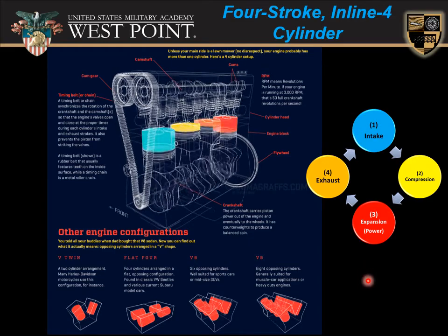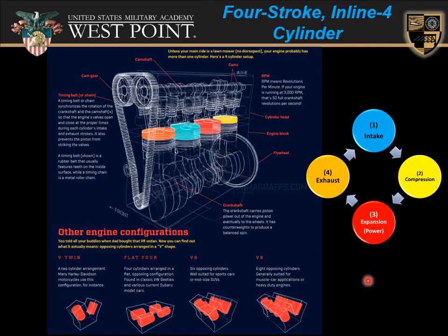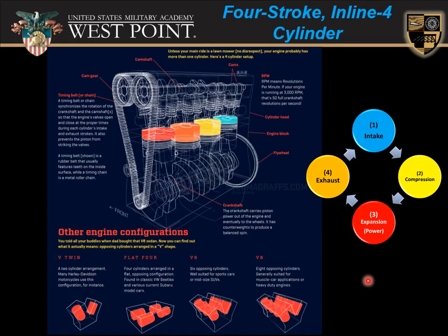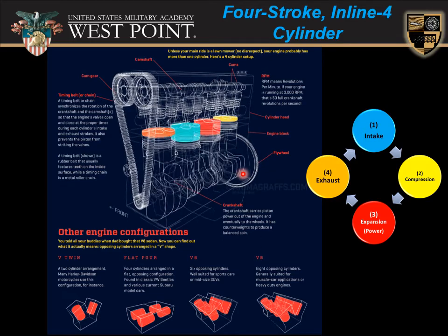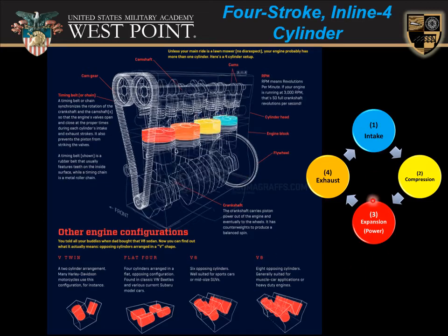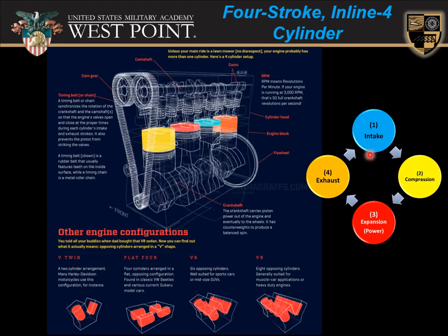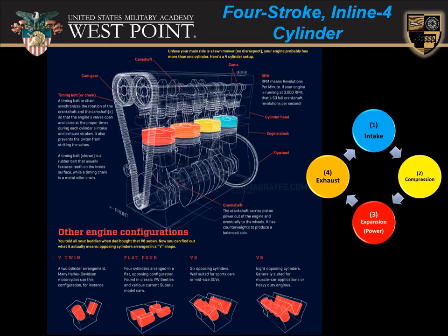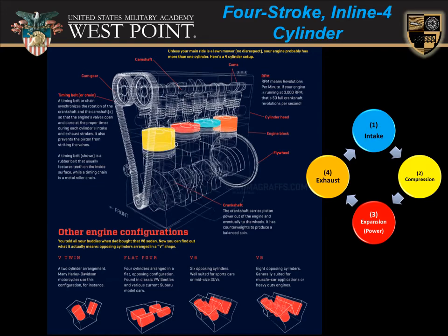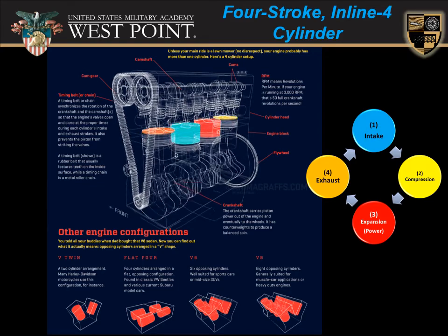So there's always one piston that is producing power. And you can note that, for example, 1 and 4, while in phase motion-wise, are 180 degrees out of phase with regard to what stroke they're on. Intake, while one is on expansion, one on exhaust, while the other is on compression. And the same stands true for pistons 2 and 3.